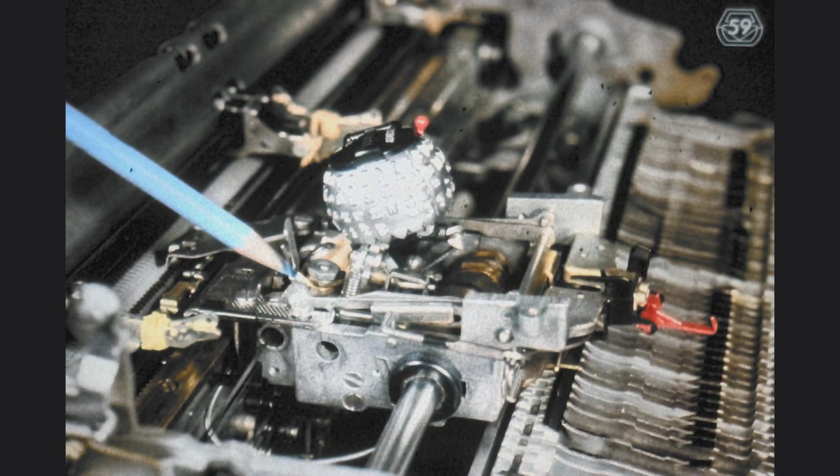After we have completely loosened one of the set screws, we cycle the machine until we can comfortably reach the second set screw with a spline wrench. Then we wedge a wide screwdriver between the print cam and the detent cam without exerting any force on it. The screwdriver, used as a wedge, enables us to loosen the second set screw without completely losing the position of the detent cam, since it is holding all of the detent spring tension.